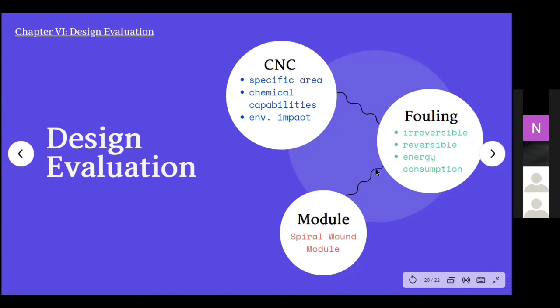Choosing the spiral wound-shaped module will bring ease to its user, for one of its advantages is easy replacement of its module elements. The configuration also provides high packing density, leading to high membrane surface area.